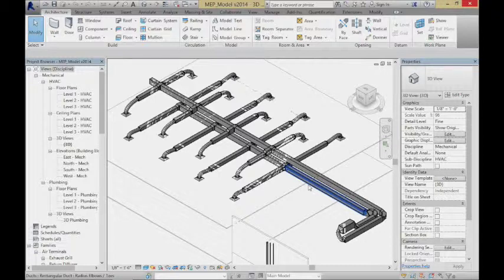So the amount of space I may actually have available to my ductwork can get very small. You could run up with only 12 inches in here, or 18 inches in here, or maybe 24 inches in here. But within that space, I have to get not only ducts that are pushing air out, but also ducts that are pulling air back in, without having to bump into each other all the time. So it really gets to be kind of a sneaky wiring nightmare to try and get it all in there and route it all.